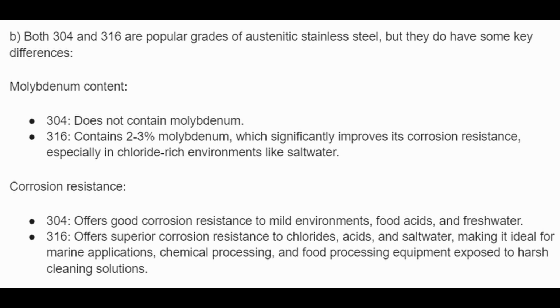Corrosion resistance. 304 offers good corrosion resistance to mild environments, food acids, and fresh water. 316 offers superior corrosion resistance to chlorides, acids, and salt water, making it ideal for marine applications, chemical processing, and food processing equipment exposed to harsh cleaning solutions.